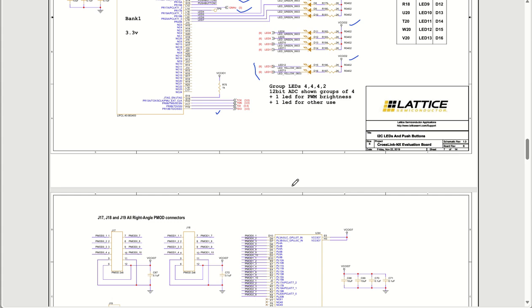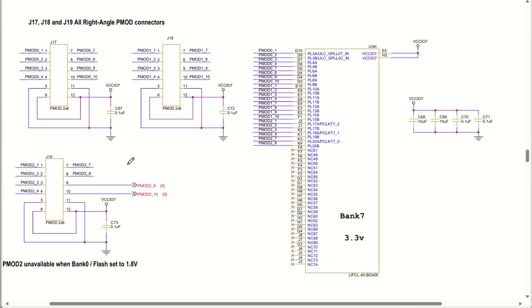All right, let us move to the next part. We have PMOD connectors as well. So you can see you have three PMOD, 1, 2 and 3, and PMOD connectors can be used for various applications like connecting your external interface boards with, let us say, I2C, UART or some SPI configuration application. Some temperature sensor or pressure sensor, any sensors kind of thing, they are compatible with PMOD connectors.